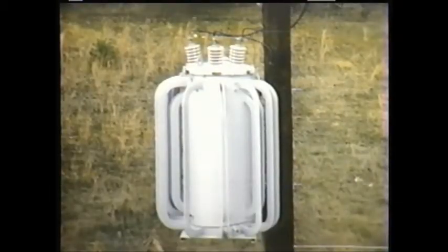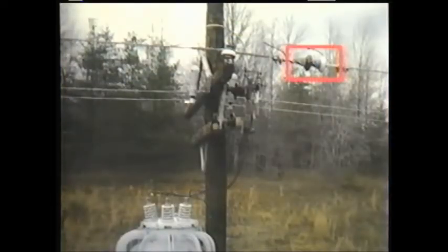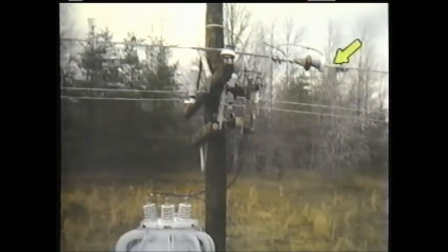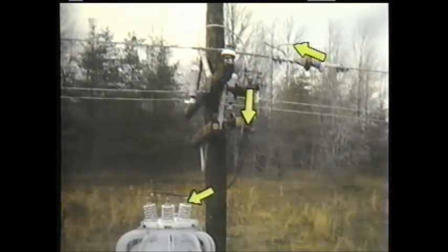One way of identifying a voltage regulator is the manner in which it fits into the distribution system. A disc or other insulator is usually installed in the distribution line near the regulator. Unregulated voltage is applied to the regulator from a tap on this side of the insulator. A wire runs from the tap through an isolation switch to the line side of the regulator.